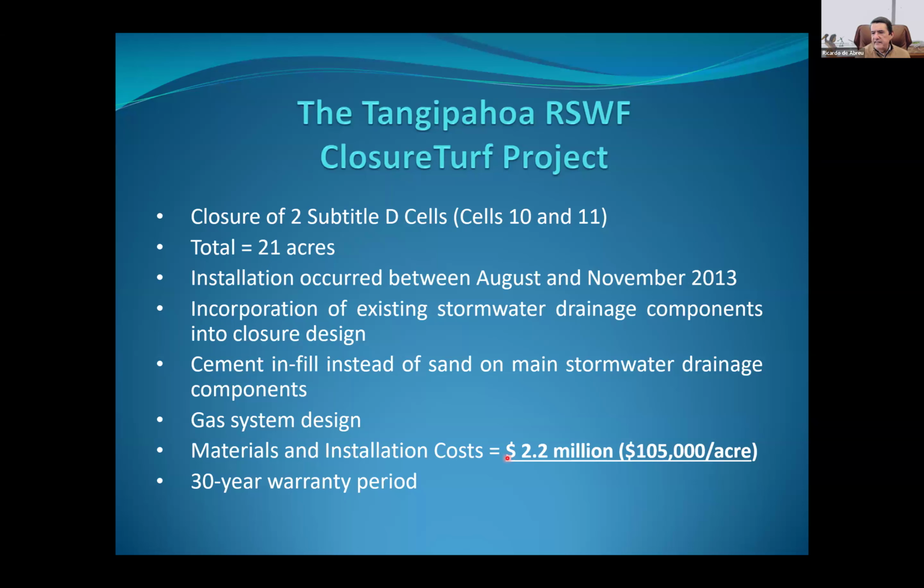Materials and installation cost at that time was 2.2 million. That's only materials and installation, not CQA or design or any other soft costs. That represented $105,000 per acre. And the installer company gave a 30-year warranty period that would cover all the post-closure period for the landfill that they are required to keep.